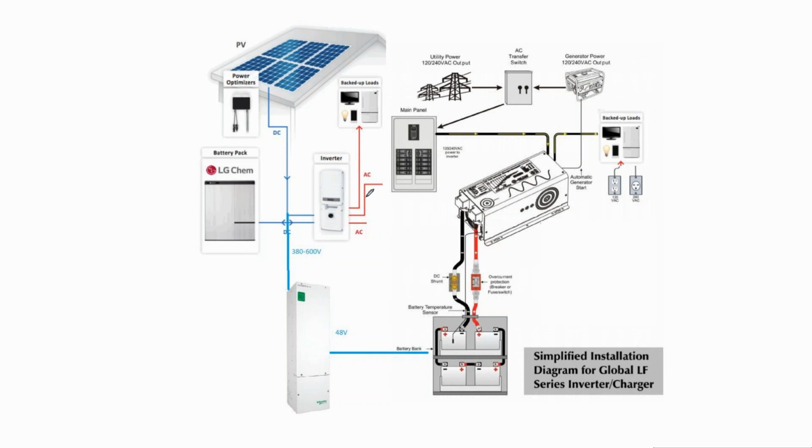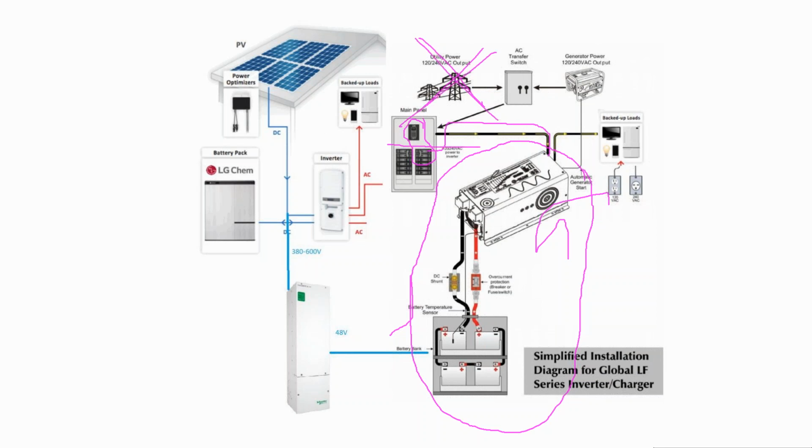But still, most solar customers want to have whole house power during a blackout, even if they remain grid connected. And so you could get a cheaper off-grid battery inverter that's not designed to backfeed onto the grid, and then land it at the top of the bus bar on a generator interlock. That way, if the grid goes out, you can flick on that generator interlock, turn on your larger lead acid battery bank and battery inverter, and then trick your batteryless solar array into turning on.